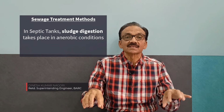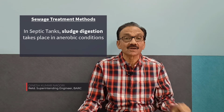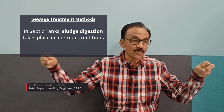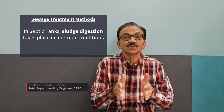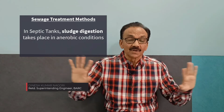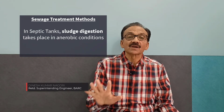People have gone to clean the septic tank or a sewer line and died because of the foul smells. So those precautions you must take. Even in a sewer line, while cleaning chambers and other things, you should first of all open both sides of the chamber for 2-3 hours. If you want to clean a particular manhole or chamber, open both sides of it and keep it open for 2-3 hours so that all the foul smell goes out. Then only should you clean the chambers or manholes, with due precautions.